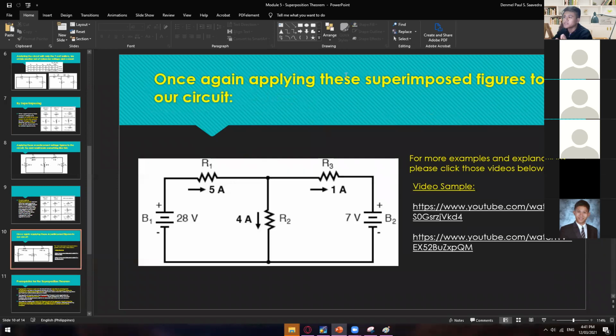Okay, so once again, applying these superimposed figures to our circuit will give you this final value. So this one will be just an additional voltage source, but we have now here a current that is flowing to this side. So 4 plus 1 is equal to 5 amps. So the same with the KCL, or Kirchhoff's law. We have another example here, so you can always visit this one. I have prepared 2, so make sure to visit those 2, because I think they will help you most to understand the superposition theorem.